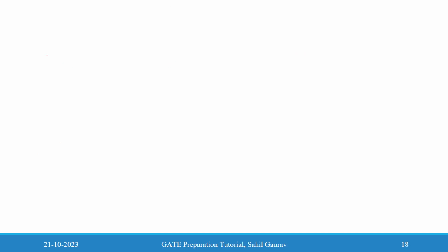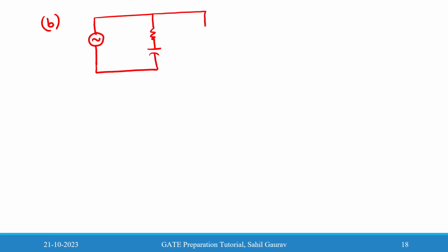So for the next problem, we have the per phase equivalent circuit, which is given like this, and the other lighting load. Lighting load always works at unity power factor. It is a resistive type of load, and it is given as 200 watt. We can take its current as I2 and the other as I1. So will this I1 current change after connecting this 200 watt load?